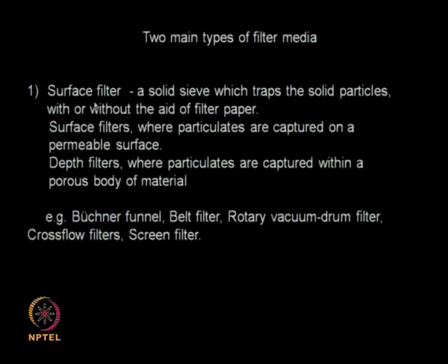So two types of filter media we can think of. One is called the surface media. This is the normal filtration where a solid sieve, it traps the solid particles. They are used in a surface filter. Then you have depth filters where the particulates are captured within a porous body.